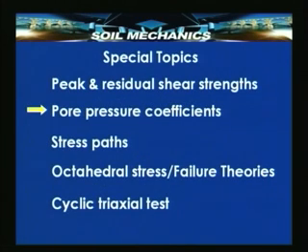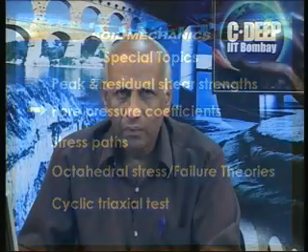Now, we will pass on to the next special topic, the pore pressure coefficient. One of the important things in a triaxial test is measurement of pore pressure during the application of the confining pressure as well as the deviatoric stress. In fact, we have seen at such great length in our previous lectures how the pore pressure varies during the conduct of the test for consolidated drained, consolidated undrained and unconsolidated undrained tests.